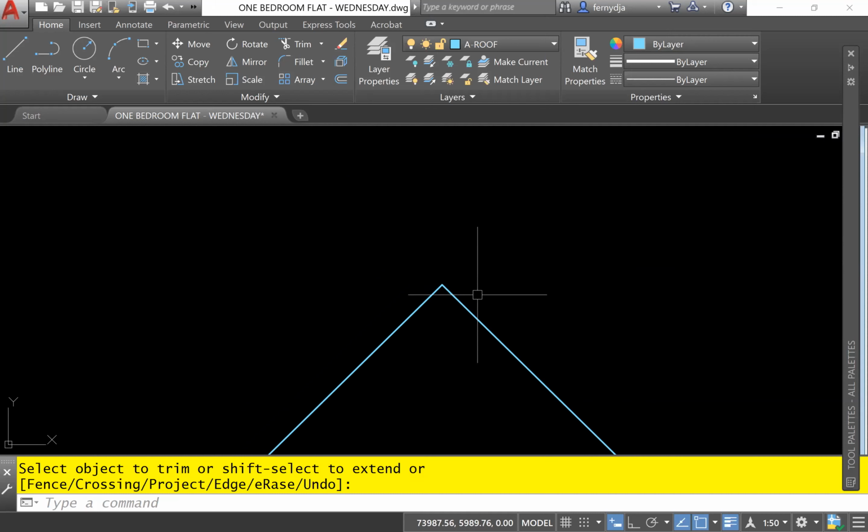All right. So what you need to know now is that these two lines basically represent the center of the rafter. The hip rafter is not just a line. It has a thickness. And when you're looking down on the roof, you're seeing the horizontal part, which is the flat part at the top. So it's 50 by 150. The 150 is the depth going down, which we can't see in plan. So we need to offset 25 millimeter on either side, since this line represents the middle of the member.